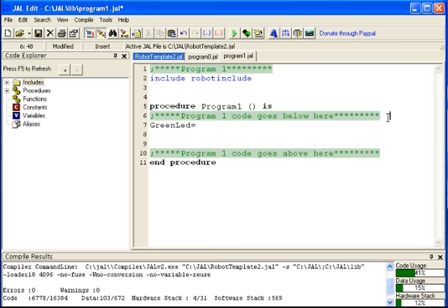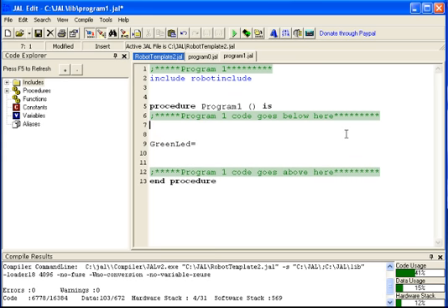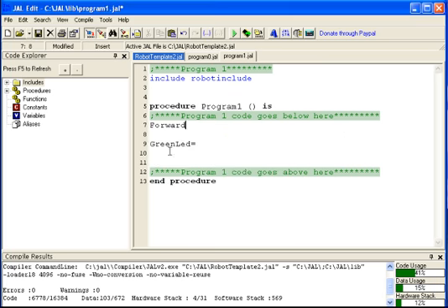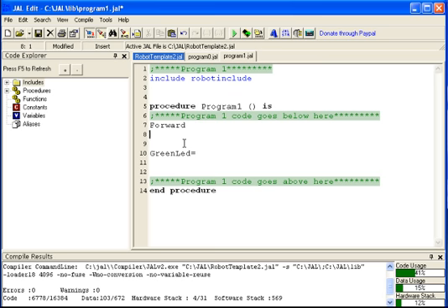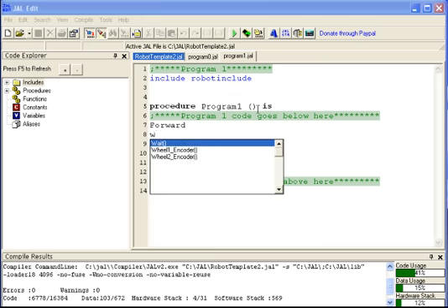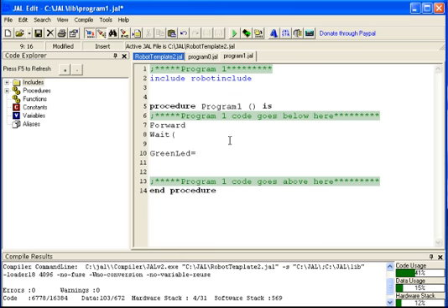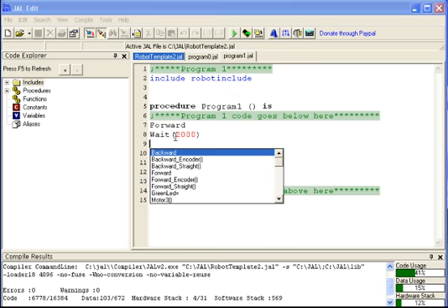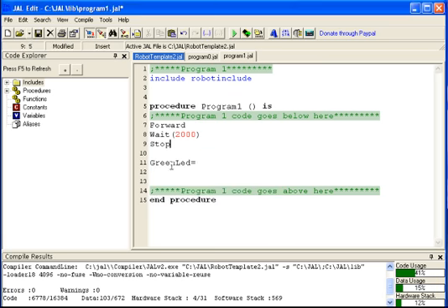How do we do a robot dance? Maybe we need to drive out to the circle. So we're going to drive forward out to the circle for 2 seconds. To do that, we give a forward command, and then we wait however long it takes to get there, 2 seconds, which should go in the parentheses here. That's 2,000 milliseconds. And then once I get there, I want to stop, right?